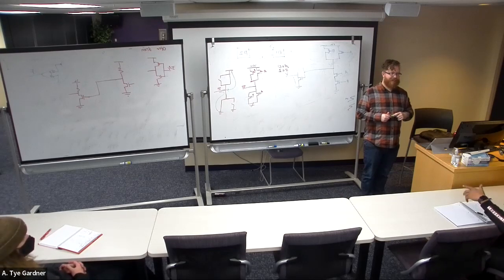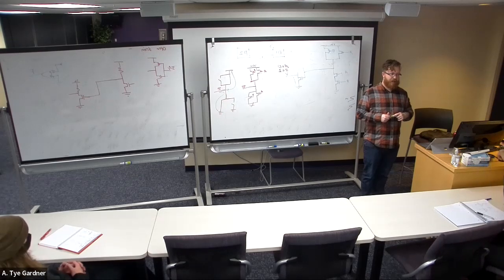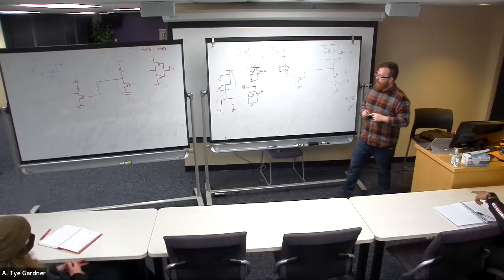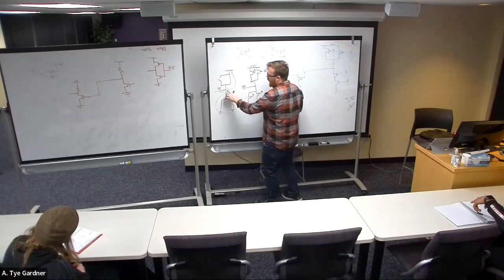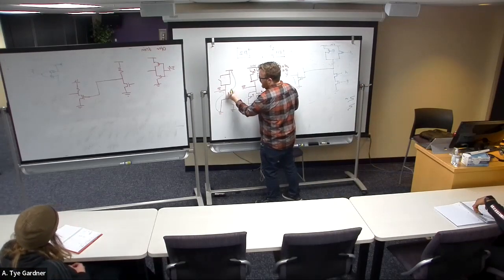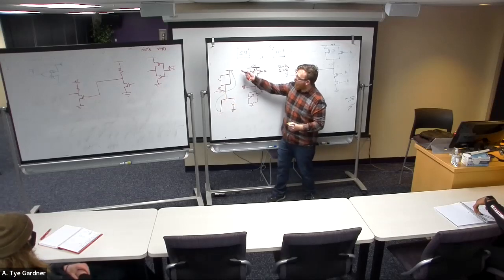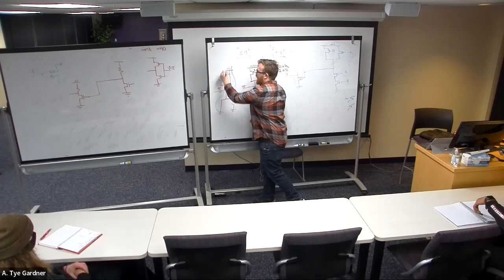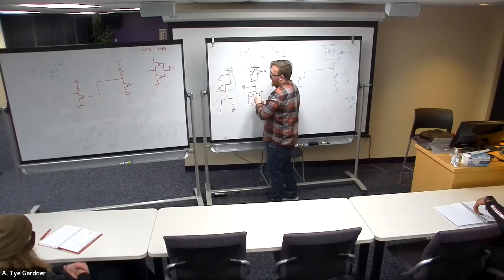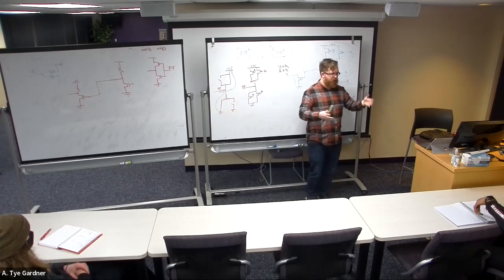I'm sorry, I might be thinking about this wrong, but isn't the power supposed to flow from up to the ground? Yes, and that's really what it's doing, right? It's flowing into this same spot. VCC is being applied to this whole wire because that wire is one node.